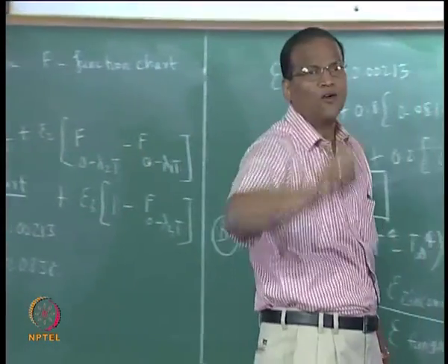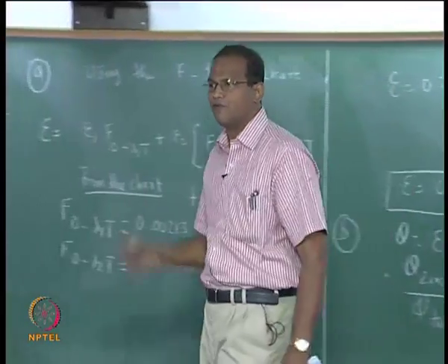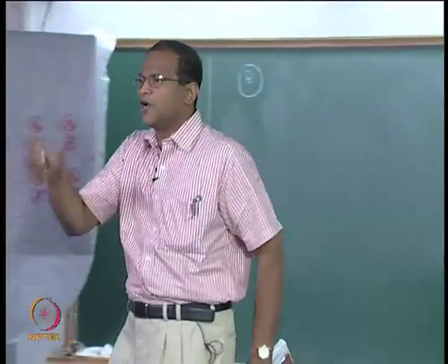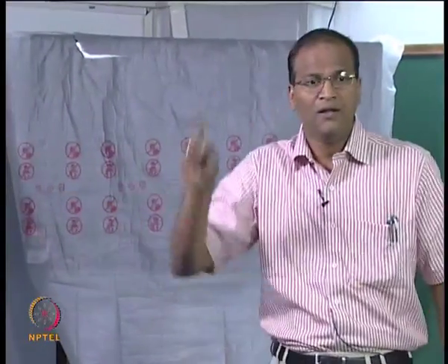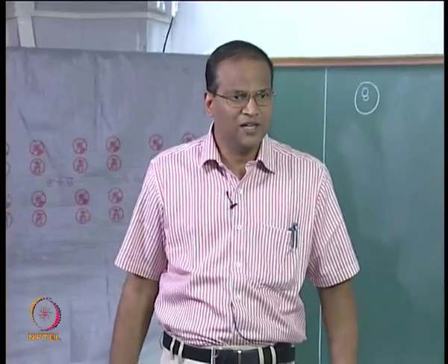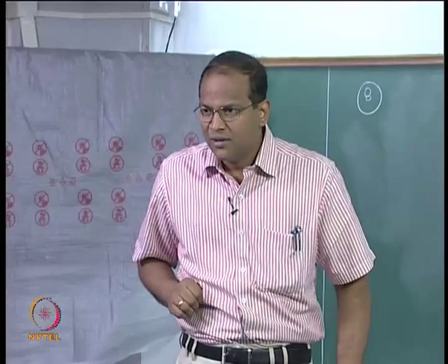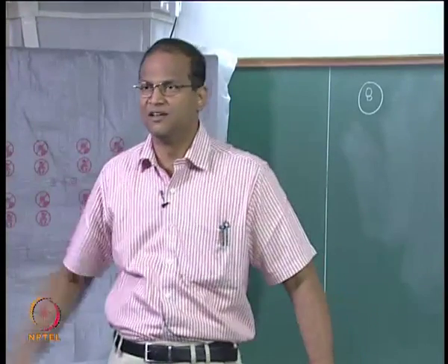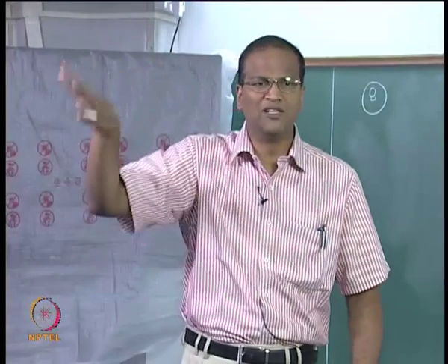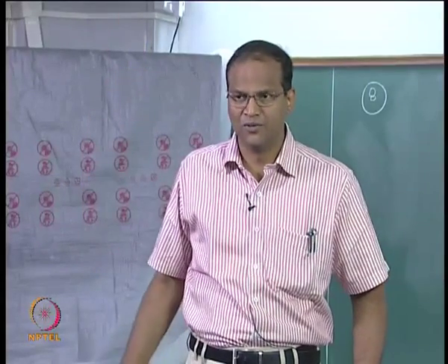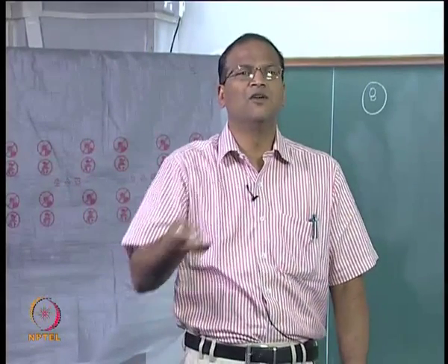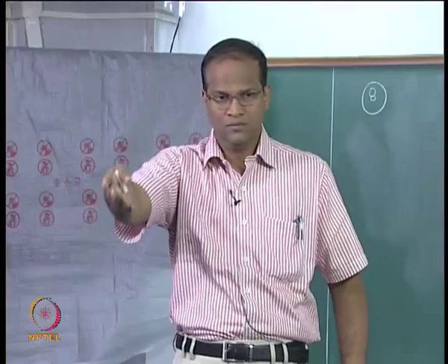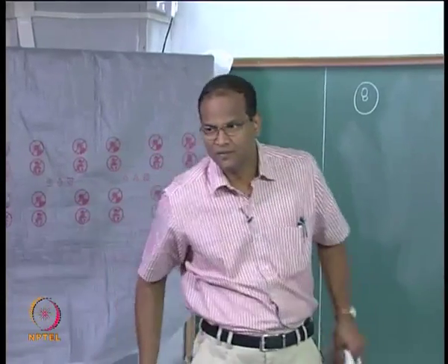The radiation which is coming out of the bulb must be equal to sigma T to the power of 4 into the black body fraction corresponding to the 0.4 to 0.7 micrometer band multiplied by the corresponding emissivity. This we can work out for both the bulbs. If you want, you can substitute the value for sigma and T and put it as a number. I would much rather keep it as sigma T to the power of 4 because I am looking only at the ratio. Then I will be finally convinced that the zirconia bulb is far more efficient. Just work it out. So radiation, no, this is 8C.